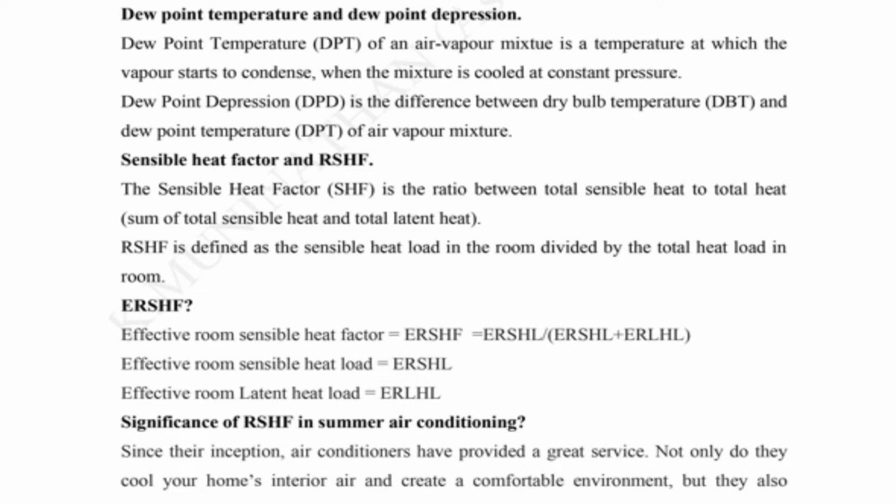ERSHF, effective room sensible heat factor. ERSHF is also equal to ERSHL divided by ERSHL plus ERLHL. Effective room sensible heat load is ERSHL, and effective room latent heat load is ERLHL. The significance of RSHF in summer air conditioning.